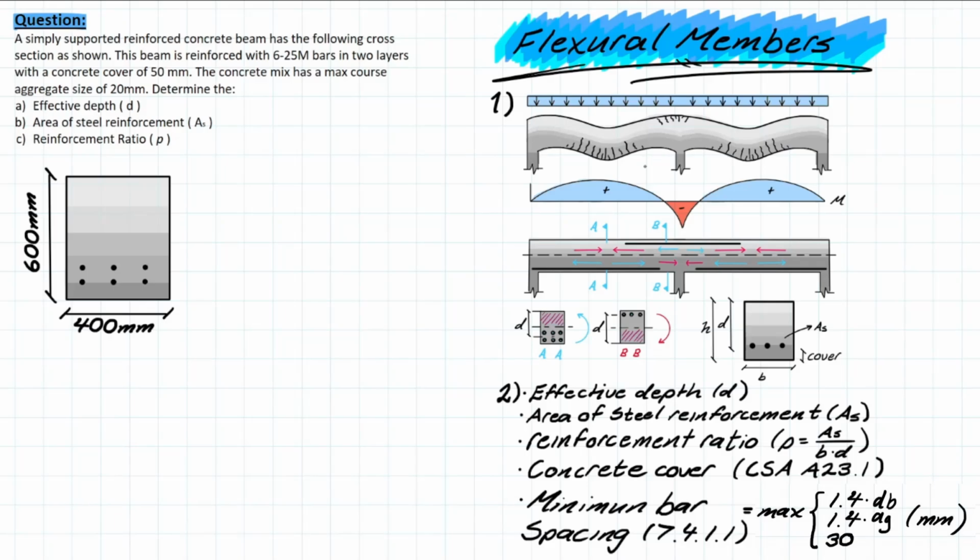So, what does that mean for concrete design? In concrete design, we talked about previously that we need to place reinforcement in these tensile regions. So, for a continuous member, you're going to have a transition between bottom reinforcement, where the tensile force is being developed in the bottom strand because of that positive moment. And then you transition to a top reinforcement that is going to be acting at the negative moment region because you have inflection. The tensile face is now changing. And that's the main takeaway for continuous members. And that's the design philosophy for how reinforcement is placed fundamentally in the member.